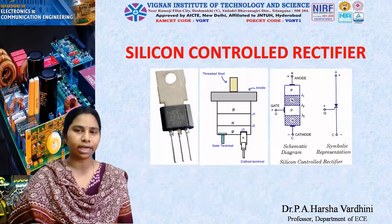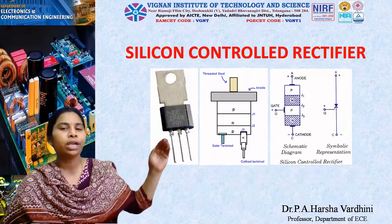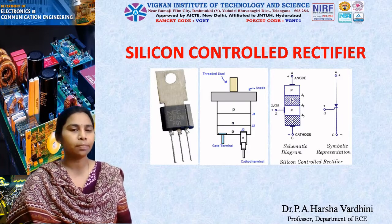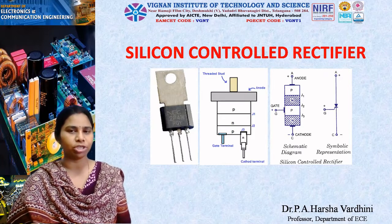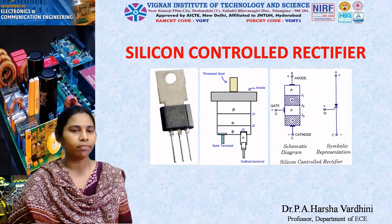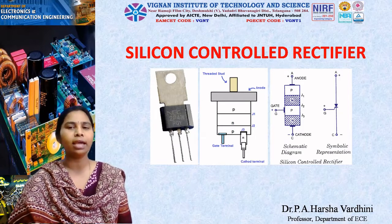As it is a thyristor, as you see in the picture, in the construction and in the representation too, it consists of 4 PN layers. The p-type material is connected to the anode terminal. The n-type material is connected to the cathode terminal, and the p layer nearer to the cathode region is connected as the gate terminal. You can see the symbol, where you have 2 terminals, anode and cathode, similar to a diode, where it can work like a rectifier.